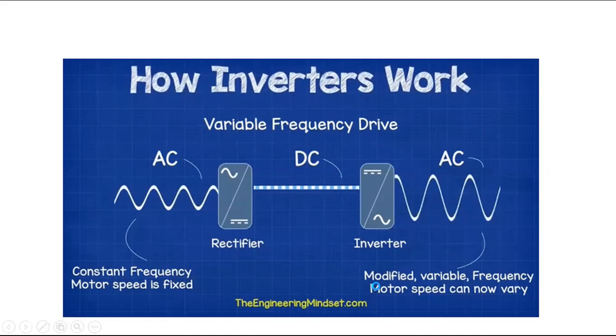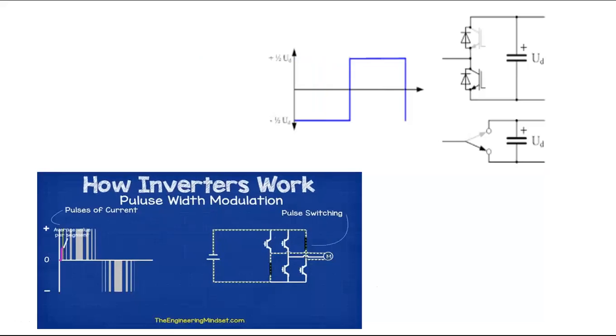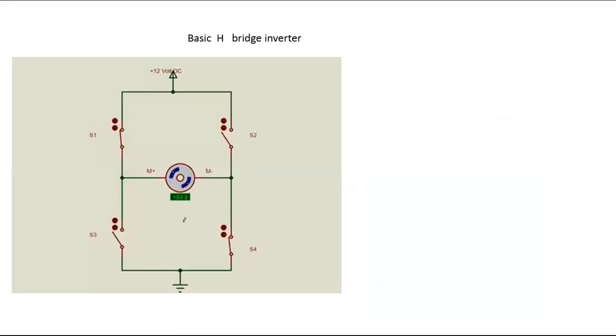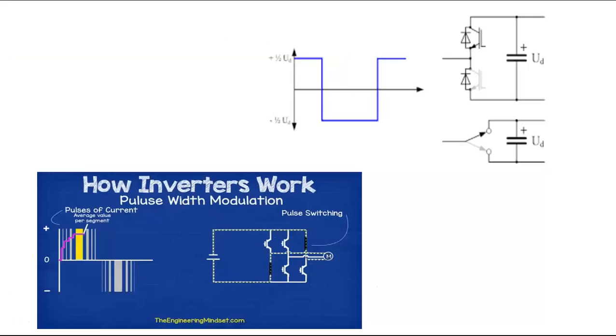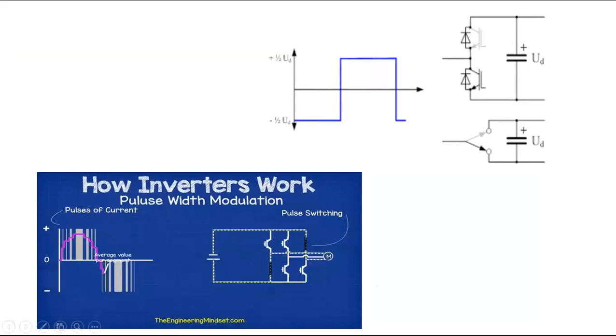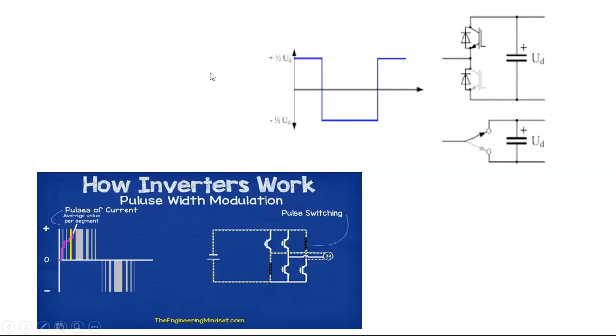So let us move to the next slide. Right. So I will discuss this particular slide, all of you. The first topic we take in the inverters unit is the H bridge inverter. The complete name is H because the circuit will be in the form of an H shape. Okay, H bridge inverter. So inverter, we are supposed to generate from DC to pure AC.